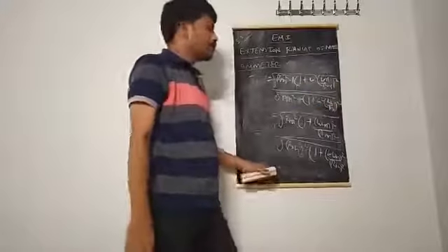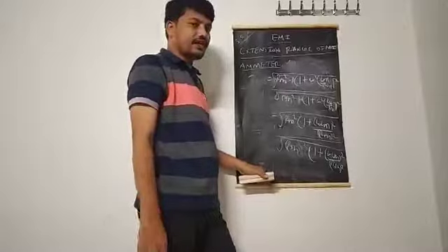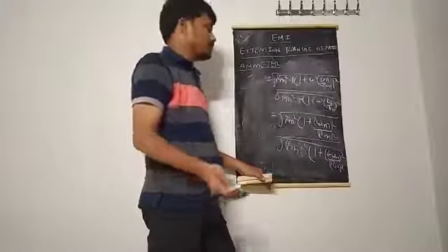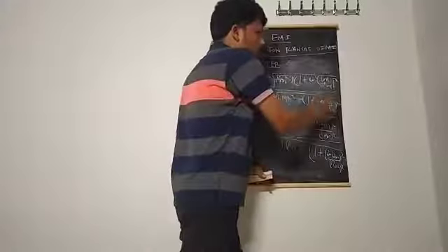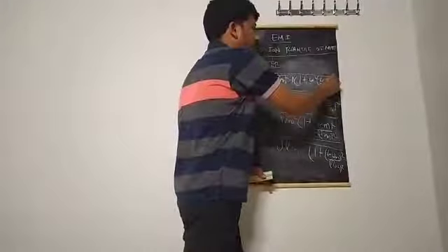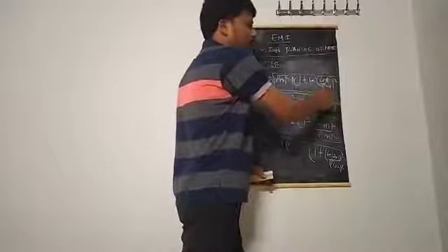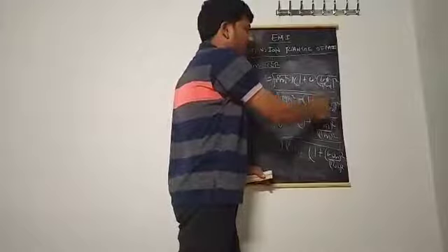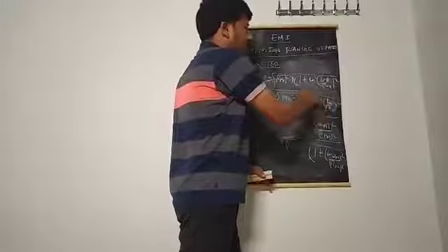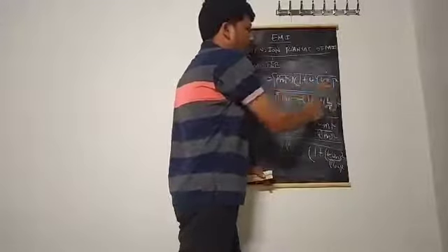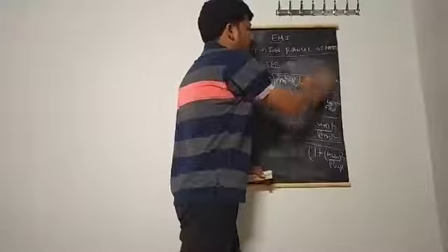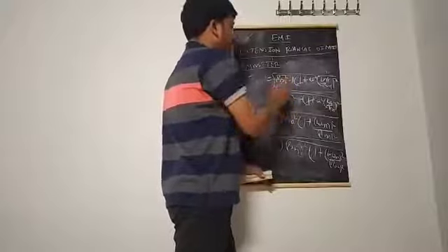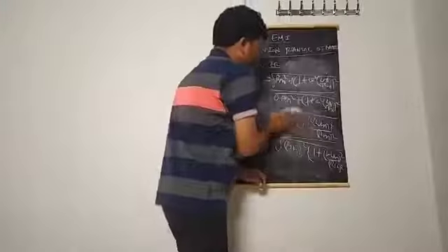We just assumed this: to make the ammeter independent of frequency, we took tau m equal to tau sh. Then what happens? This becomes equal to this. Because Lm by Rm is tau m and LSH by RSH is tau sh, and both are equal, this by this is equal. So 1 plus omega square into tau, by 1 plus omega square into tau, again this and this cancel, therefore square root of Rm square by RSH square. Finally we got this equation.